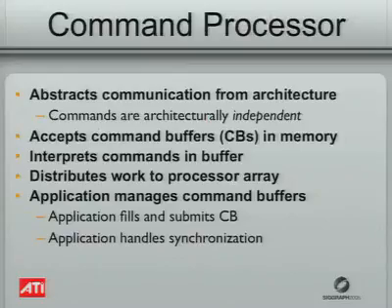So looking at the DPVM in more detail, the first major component is the command processor, and it abstracts the communication from the underlying architecture. So commands are architecturally independent, and in this sense, the command processor actually interprets all of those commands and submits them to the processor array. So the command buffers, as I said previously, are actually stored in memory, and the work that's necessary for the processor array is distributed through the command processor.